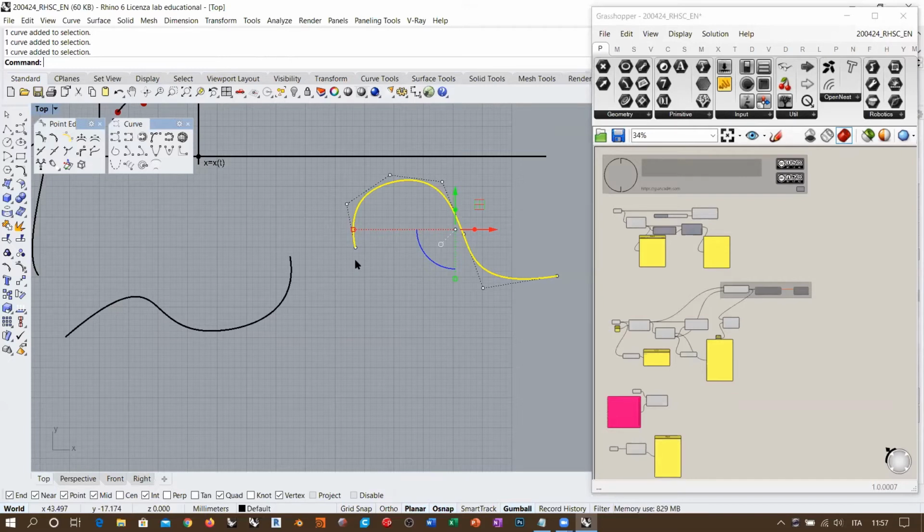Curvature is the second derivative, okay? So it's the derivative of tangency. And so curvature expresses the variation of the tangent along the curve, okay? As tangency defines the variation of the shape of the direction, the curvature defines the variation of the tangency. In what kind of design should you work with G3 or G4? This is very interesting because